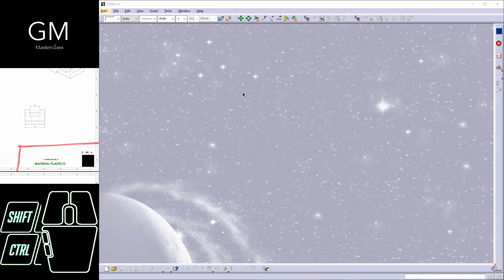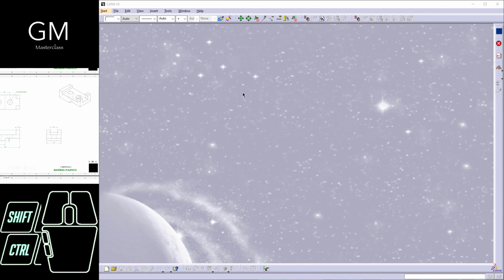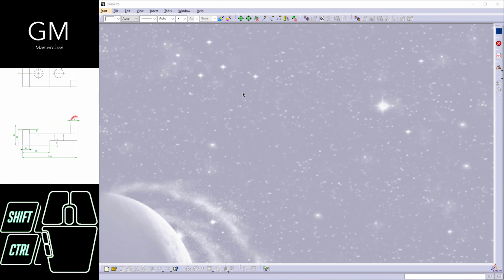Within that box, which is made taking into account the normativity for the engineering draw, it not only contains the information about the unit system, but also the information about the person who did this engineering draw, the person who checked the material, some information about tolerances maybe. But as you can see right here, there is none. So because of it, I can assume that these are millimeters.